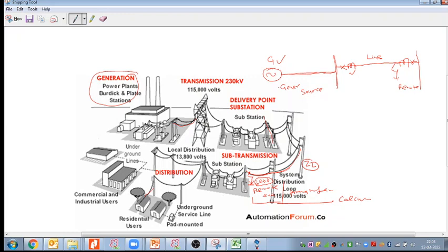Now, till here we have two types of resistance. Till this substation, we are taking the fault current as given in the tender specifications. Suppose 63 is given in the tender specifications, so we are going to take 63 kiloampere till this point. And from this point to the remote point, there are two kinds of resistance.